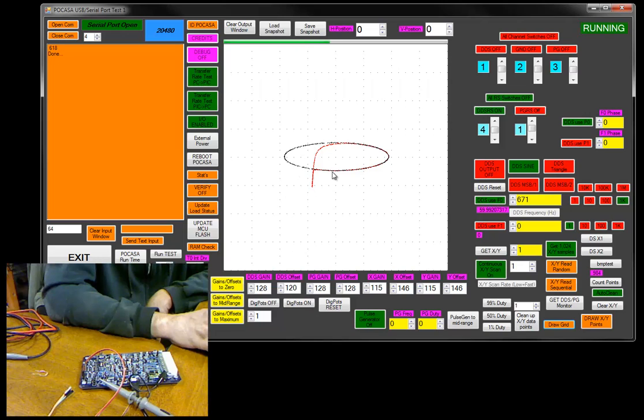And over here where the diode starts to turn on, I've still got a capacitor. I don't have a diode anymore, so that tells me that whatever diode is in that circuit is blown out. It's not there anymore. It's not modifying this. And this is interesting. I never noticed that it does that exactly like that.